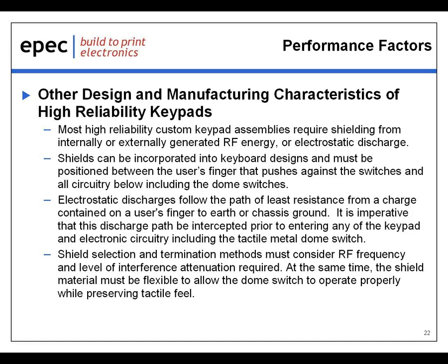Electrostatic discharges are built up by walking around in an office environment on carpeting or tile floors and then making contact with a keypad that is connected to ground. It's imperative that this discharge path be intercepted prior to entering any of the keyboard's circuitry, including the tactile metal dome switches, which are part of the circuit. Shield selection and termination methods must also consider the RF frequency involved and the level of interference attenuation required.